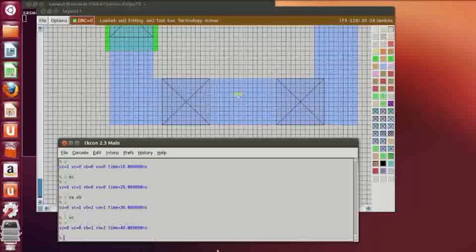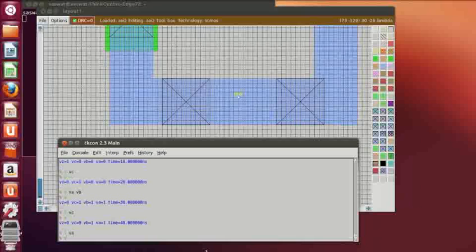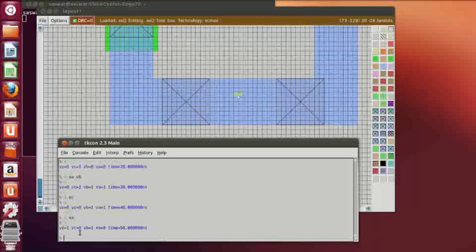So I have to give low value to either VA or VB and then S. So the output of the AND is 0, this is 0 and this is 1. If you want to see the waveform in the analyzer, then type ANA, VA, VB, VC and VZ.